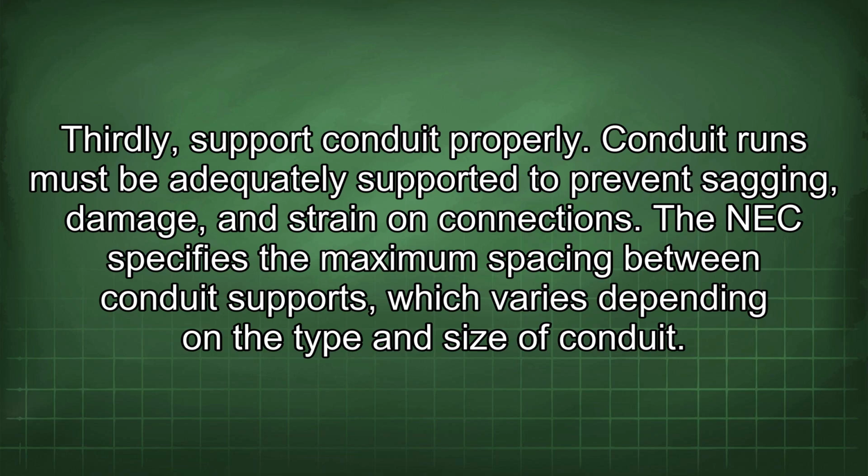Thirdly, support conduit properly. Conduit runs must be adequately supported to prevent sagging, damage, and strain on connections. The NEC specifies the maximum spacing between conduit supports, which varies depending on the type and size of conduit.